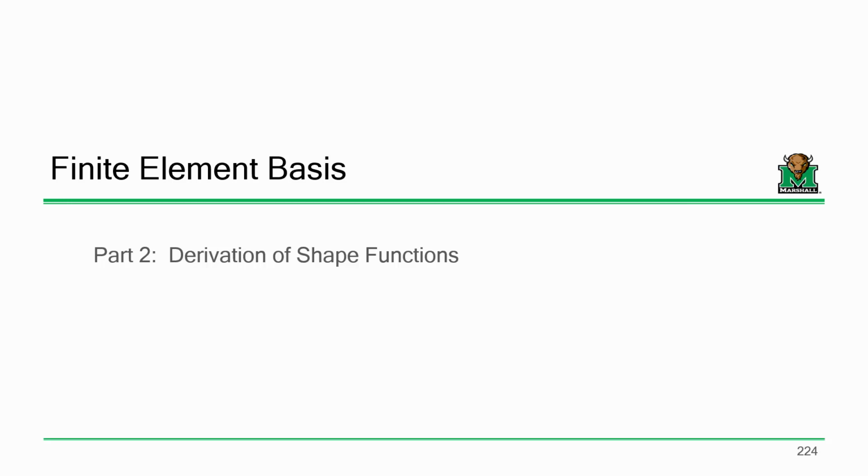Last time in terms of lecture, we reviewed our first component of the finite element method, which is the idea that energy principles should be applied. Energy going in has to equal energy going out in some fashion or another. We can use energy principles for basic problems like those involving linear structural mechanics, which is what we've been doing up until now. But we can also apply it for more complex stuff, like what we might see later with vibration and things like that.